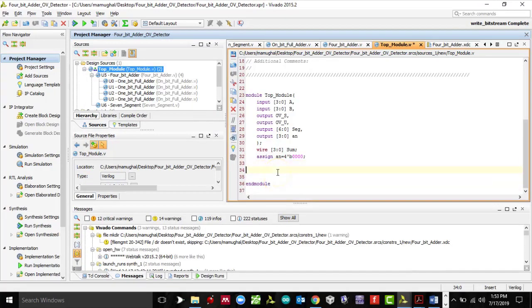All right. In order to finish the code, we're going to have to add the 2 modules, so instantiating the 4-bit header and 7 segment modules here. I'm going to have to make sure that the name of the module exactly matches with the one that I have over here.